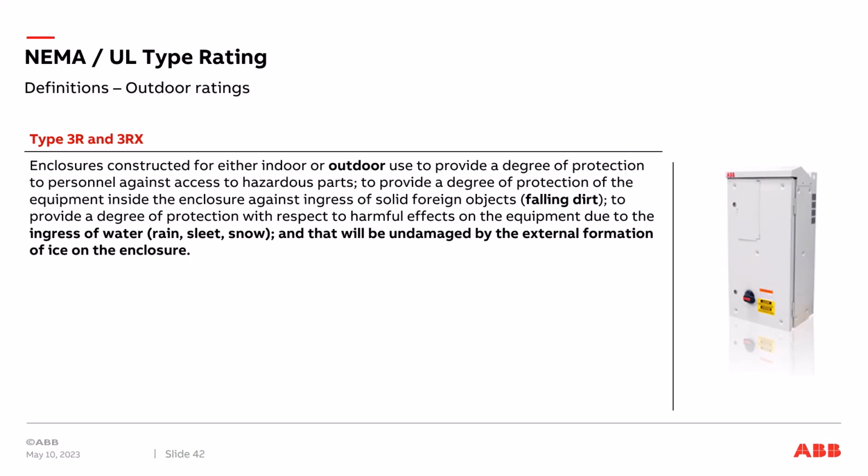ABB has a Type 12 enclosure system for the base drive that's very cost effective. A Type 3R and 3X enclosure is designed for indoor or outdoor use. It gives you a degree of protection against personnel and falling dirt. It also protects you against the ingress of water, rain, sleet, or snow, and will be undamaged by external formation of ice on the enclosure. This does not mean you can wash it down with a garden hose. It's just for rain, sleet, or snow.